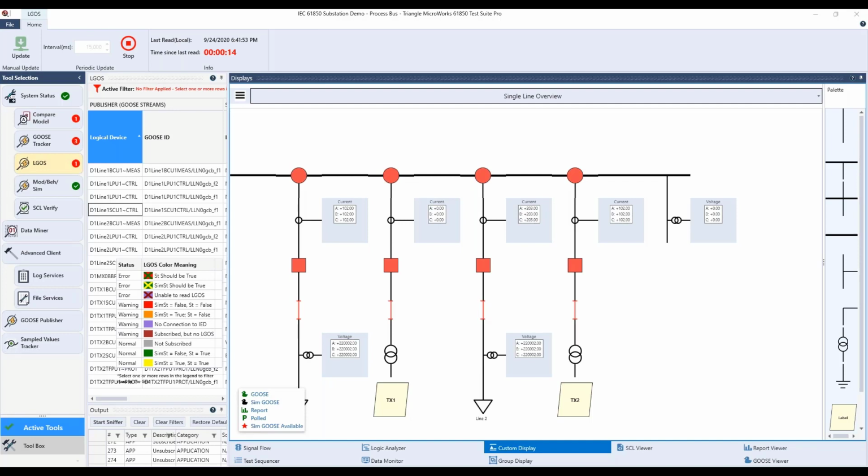And we will simulate a non-permanent fault. That means a fault that is cleared by the reclosing. So what we should see is the breaker to open, and after a while to close again and remain closed. So if you observe this breaker while I start the test, you should see it quickly turn green and then turn red again. If I click now, it turns green and it goes back. It was apparently a successful reclose.